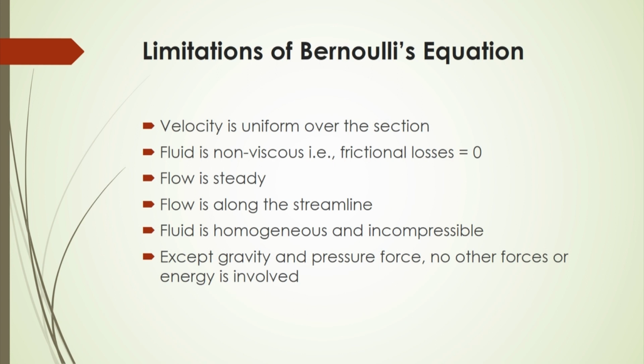If the flow is not along a streamline, suppose it is vertical or some other form, then you cannot apply this Bernoulli's equation. And in the case of fluid where homogeneous and incompressible conditions are there, then only you can apply the Bernoulli's equations. Also, except gravity and pressure force, no other forces or energy are involved in this Bernoulli's equation. So, these are the limitations of the Bernoulli's equation that you have to remember. Whenever you are going to apply these Bernoulli's equations, you have to keep in mind these limitations.